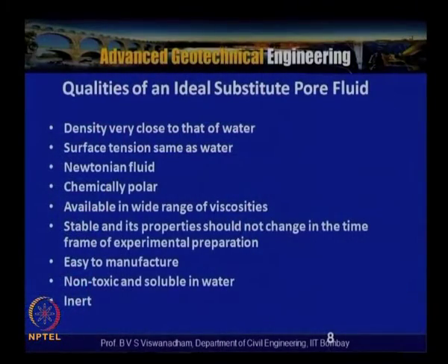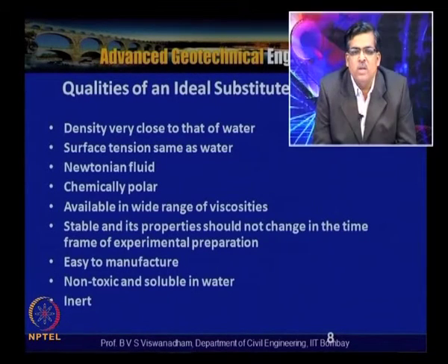So once again, the qualities of an ideal substitute pore fluid. One is that the density has to be close to that of water, and this is very much required to have identical effective stresses as in the prototype. Suppose you select a pore fluid which is heavier than water, for example zinc chloride solution, then we cannot simulate this identicality in the effective stresses. And the surface tension should be the same as that of water,